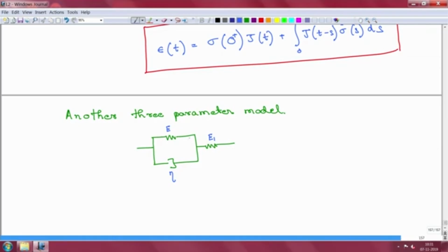The Kelvin Voigt we know already has a solid like response, because for a finite force the displacement of the system is bounded, is going to be finite, and the same holds true for the spring. So, even when you put these two together, where for a finite force the displacement in both of them is going to be bounded, this represents a solid model. So, this is appropriate for a viscoelastic solid. So, this is a Kelvin Voigt Maxwell model. Or sorry, I forgot Maxwell, but okay. When you say Kelvin Voigt, you know Maxwell's name should also be there.